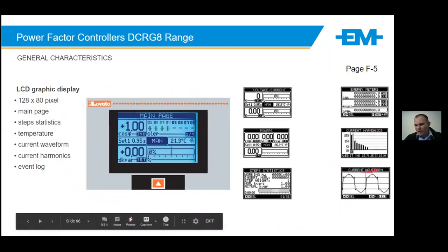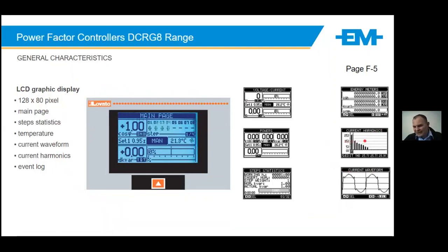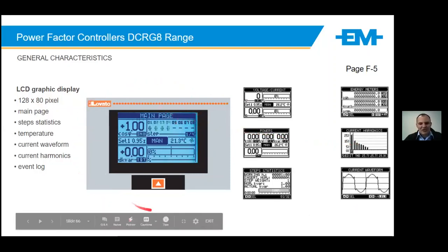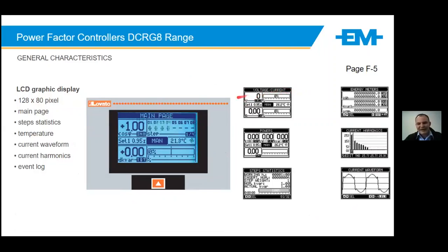Quite often I would go into this graph page and I could see right there, without using any other power quality analyzer, that, wait, you do have a current harmonic. And based on thresholds set against THDI, I can disconnect the system. So it's quite flexible on taking different variables and customizing that as an alarm, and on the event of that alarm to tell the system to do this or do that, like disconnect the steps and so forth.